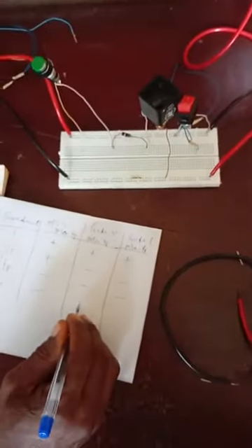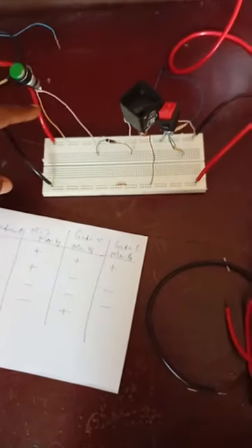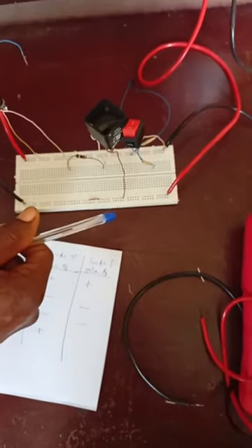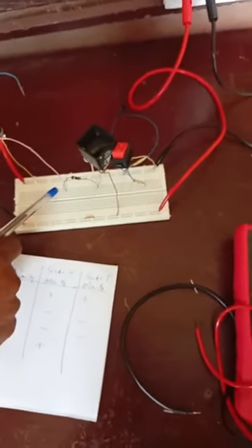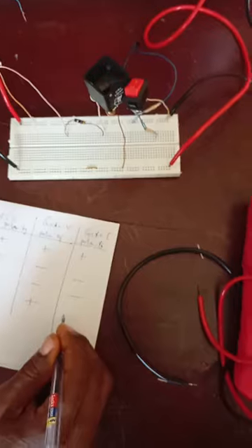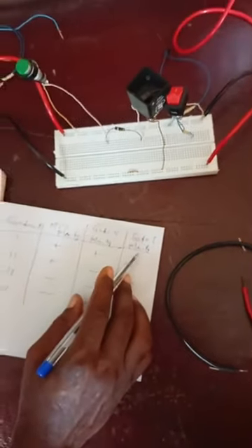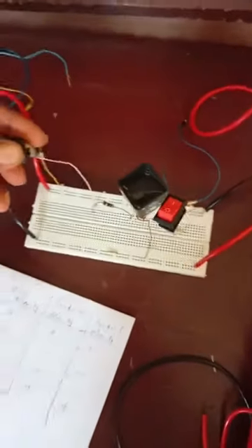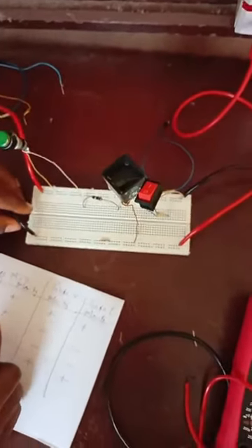It means that we still have negative at the main terminal, the AC source, and on our DC source, the positive terminal is the gate source. So the current will now flow from the gate to the main terminal because we have a positive terminal at the gate. Current will flow from positive down to the main terminal. That's positive gate polarity current. Let's now see if that Triac is still going to operate in this condition.